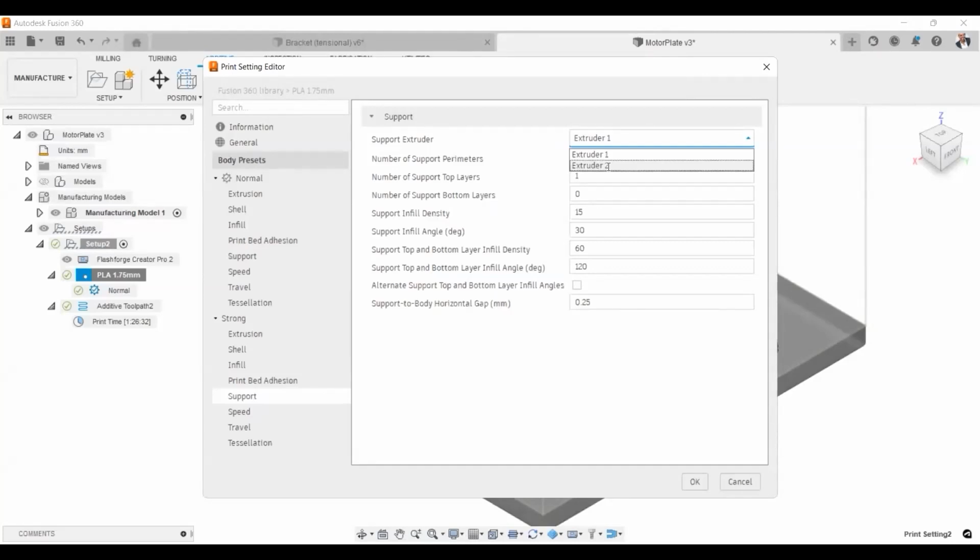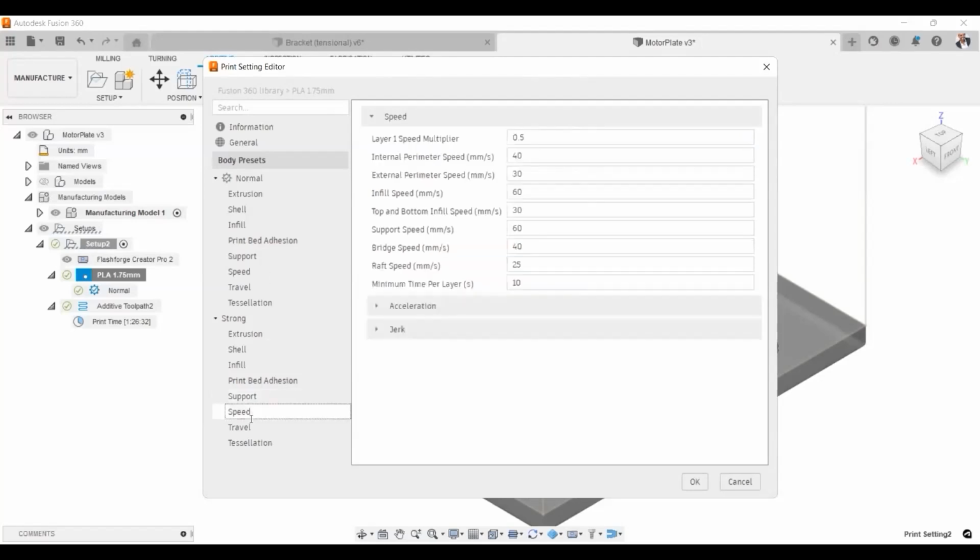So that's why those filaments are made specifically as support materials, because they can help you remove the supports, and also help you get better surface finishing even with support, than if you didn't use supports that are dissolvable in alcohol solvent or in water. You're also seeing that the support speed settings here are different from the settings here. Some are quite the same, some are different.